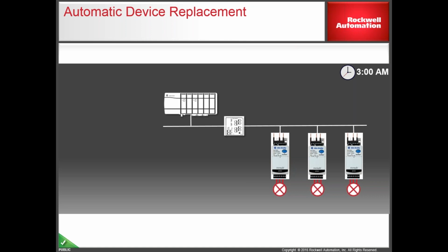What version of Logix constraints are there? It's tested down to version 16 of RSLogix 5000. With version 6 firmware, which is the latest release of firmware, we're limited to version 20 of Logix or greater, and then version 24 or greater of Studio 5000.